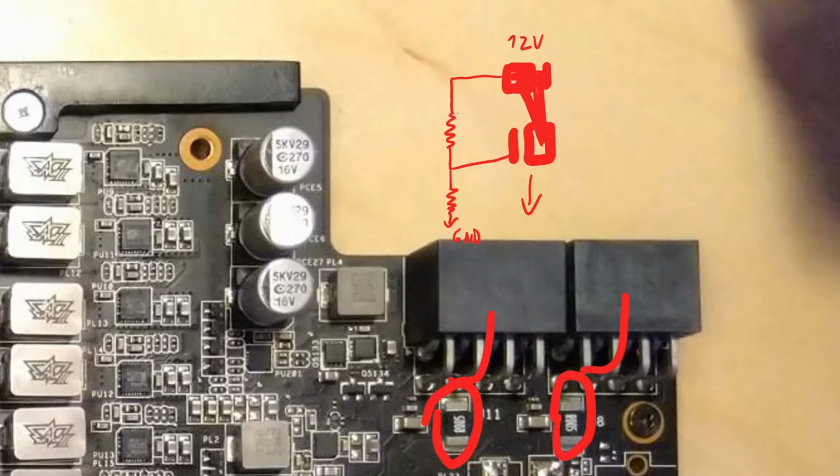So what you can do is you remove the shunt, you bridge the 2 pads on the 12 volt side, and then you bridge those 2 pads to the power pad of the output side and leave the current sense pad on the output side empty. What you then do is you create a voltage divider and connect that voltage divider, like I've put down here, to the sense pad on the output. And whatever resistors you choose for that voltage divider, you can completely fabricate a reading for the INA3221.